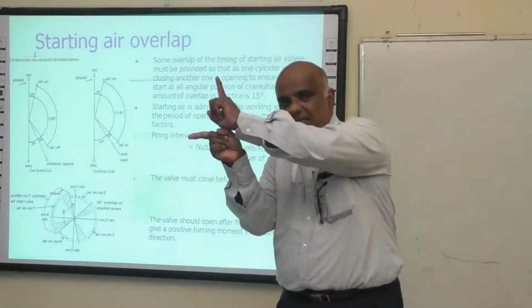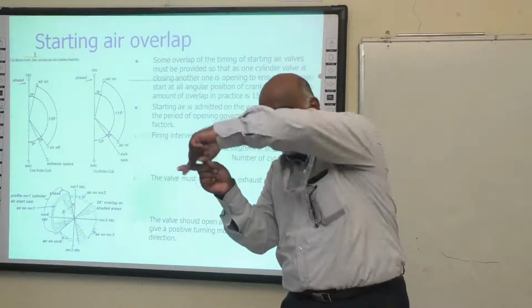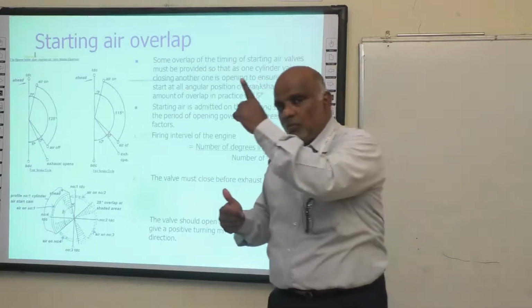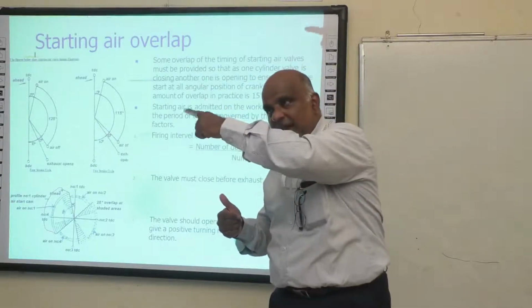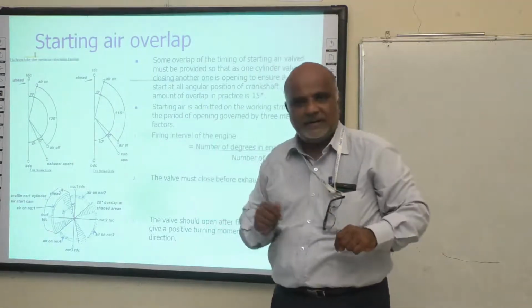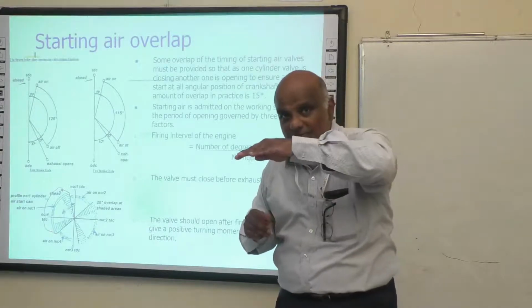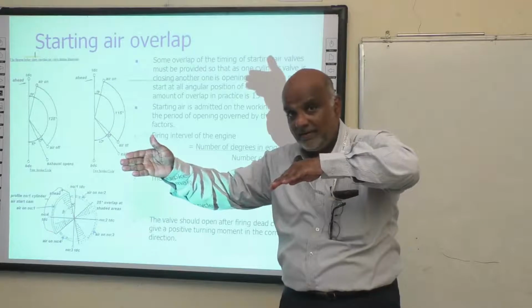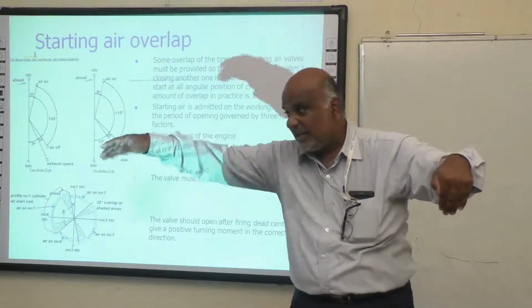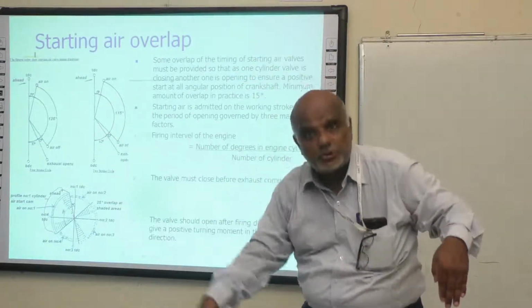Now 0 to 60, when I admit the air from 0 to 60, then from 61 degrees onwards, if I go to number 5 unit, what's going to happen is, 0 to 60 when I admit in the air, at the 59th and 60th moment when I'm shutting off the air for the first cylinder, as per the firing order, the air is getting shut off because I don't need any more air there, and I want the air here at number 5 unit. Now, when I shut the air at number 1 unit, the engine RPM will reduce.